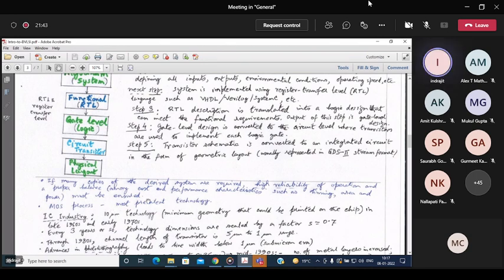And the MOS process, this is the most prevalent technology. You may know that in different circuitry, like space circuitry and so on, electronics engineers have used MMIC, that means monolithic microwave integrated circuits, built on gallium arsenide or MESFET. They provide us with good speed, but on the downside, the area requirement is large at the very beginning, the processing technology is quite complex, and power consumption is huge.